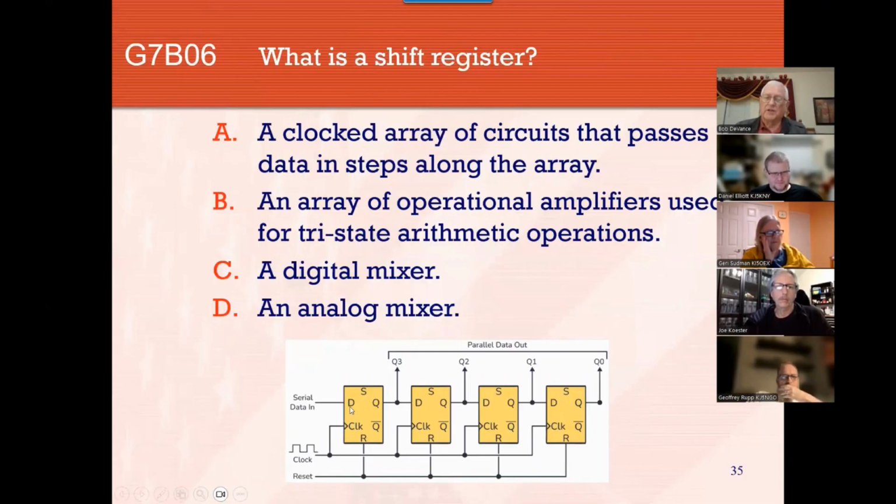And when the clock signal hits it, it tells this output over here, emulate whatever that input was. So if it's a 1, it switches this to a 1. And then it sits there. Then this 1 is now sitting on this flip-flop. The next clock cycle, that 1 gets transferred across. Next clock cycle, it goes to the next one. Next clock cycle, it disappears or goes to the output.